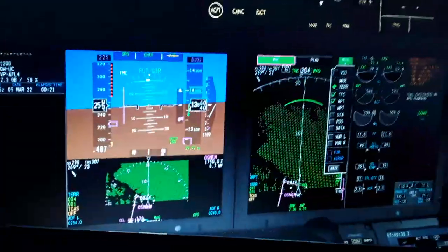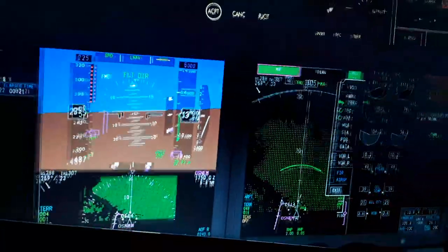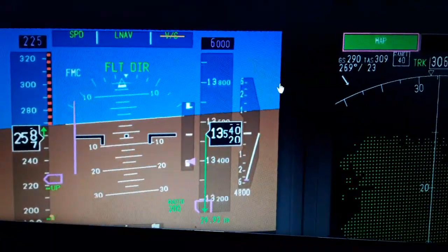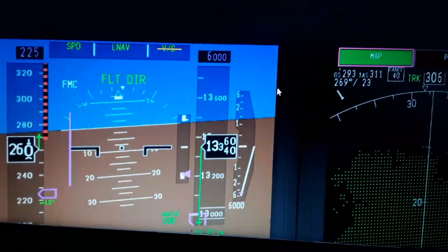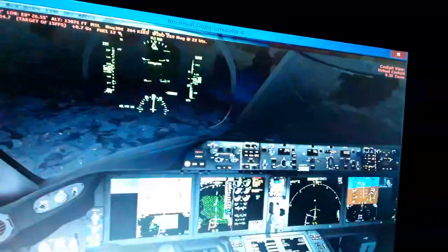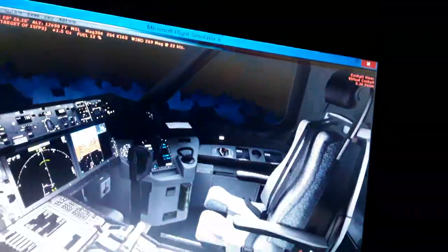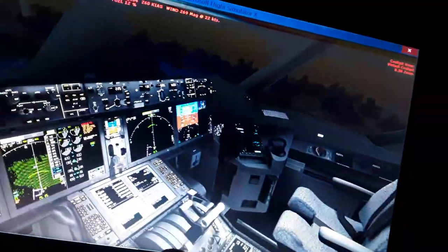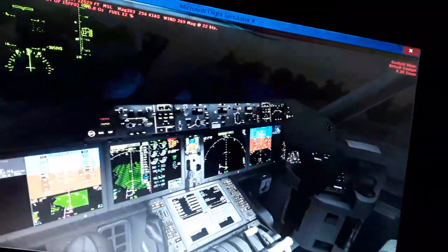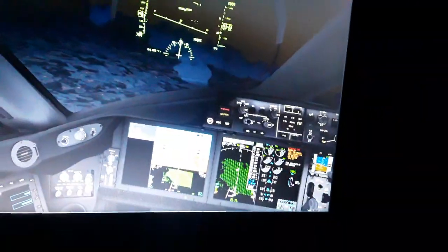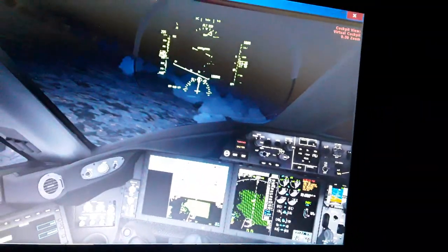So we have it now, the airspeed commanded, 13,000 feet. And we need to level off. Also use some flaps as we are descending, and we need to turn to the runway.